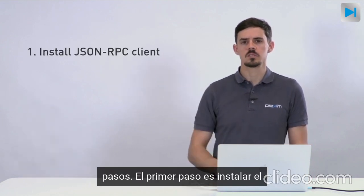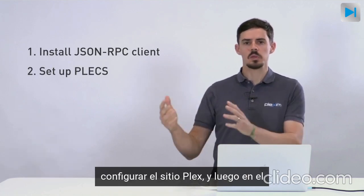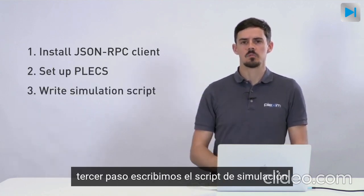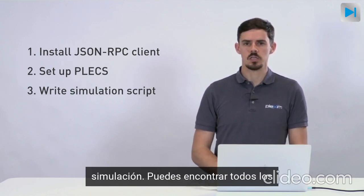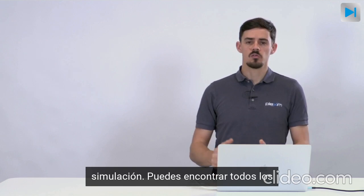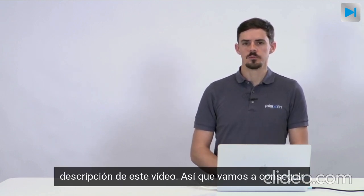The first step is to install the JSON RPC client. The second step is to set up the PLECS side, and then in the third step we write the simulation script that calls the PLECS Standalone simulation. You can find all the resources for this short tutorial in the description of this video.